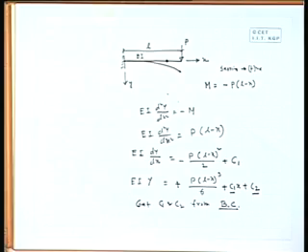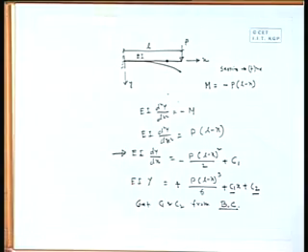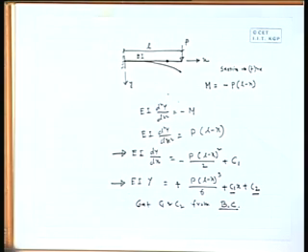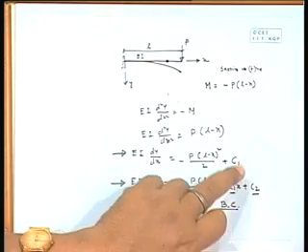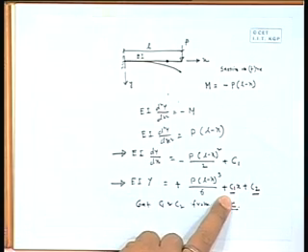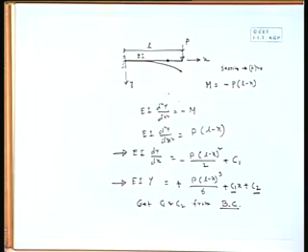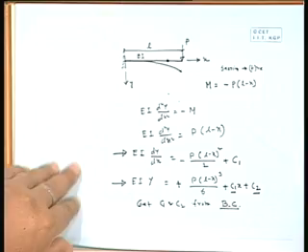So, first of all at this level we put at x equal to 0, d2y by dx2 equal to 0, and at the second level we put at x equal to 0, y is equal to 0. So, first we will get the C1 value, you can substitute here, and in the second level once you put the requirement for deflection equal to 0, we will get C2, right.